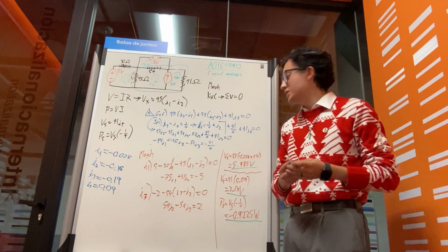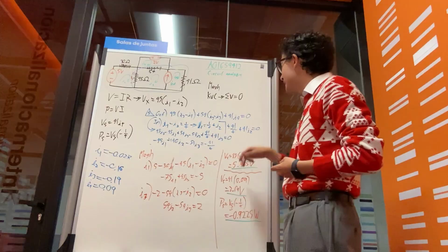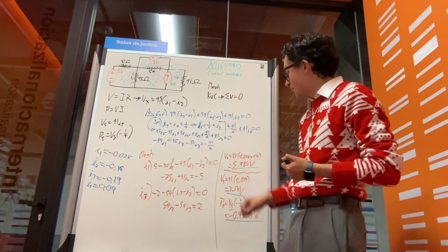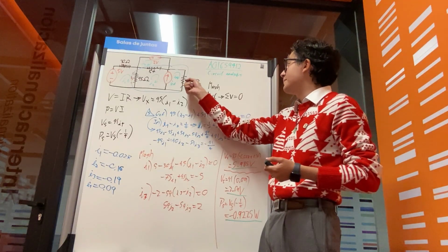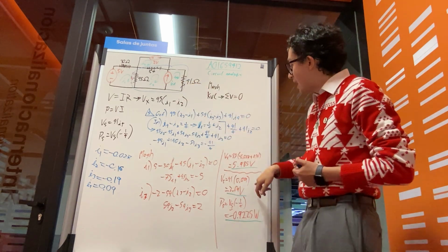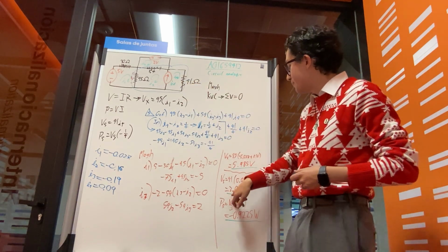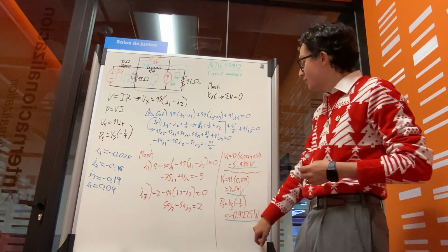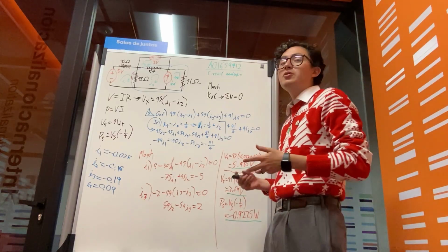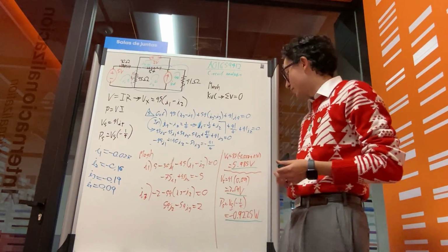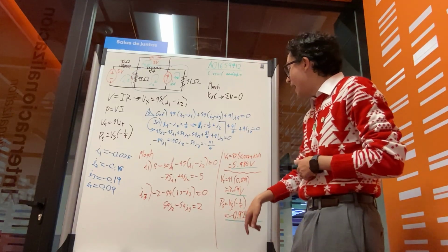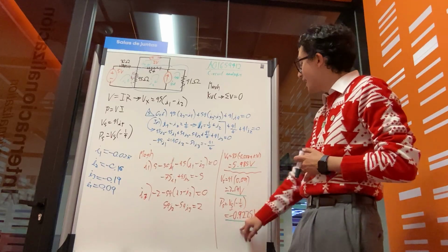After making all of these calculations, we obtain that the voltage Vx is 5.9. In the case of the power source, first we obtain, as I mentioned previously, the voltage passing through this resistance, which in this case is 3.6, and once we obtain it, we are finally able to obtain the power source. What is the power being delivered by the power source? In this case, it is negative because it is an active component, and it is 0.9 watts.